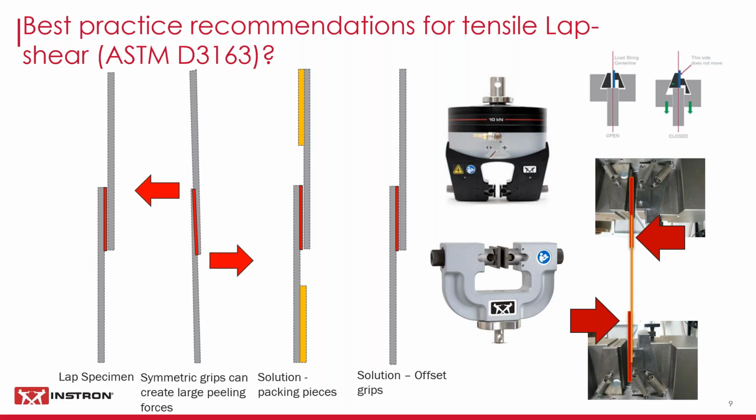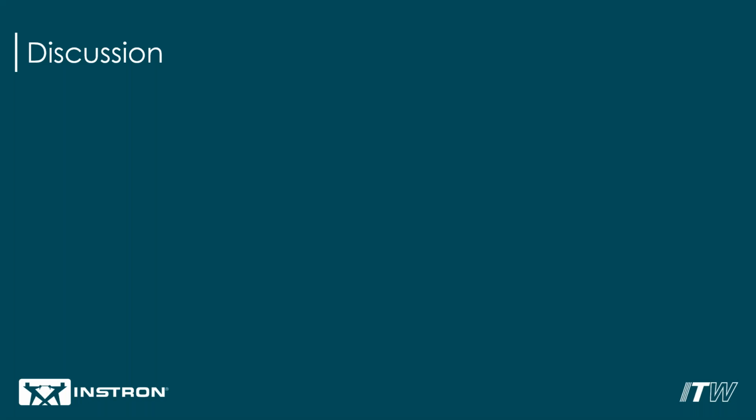Great. We had another one here, which wasn't covered in the slides, I guess: to find Poisson's ratio, how can you calculate both the lateral and linear strains at the same time? Okay, well, I guess there are two solutions to that. One would be to use bonded strain gauges, an axial strain gauge and a transverse strain gauge, or maybe 4 gauges total if you have them on both sides of the specimen for averaging. So bonding 4 gauges and then conditioning 4 gauges.